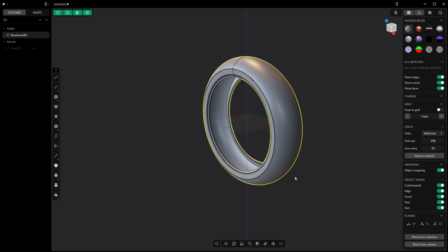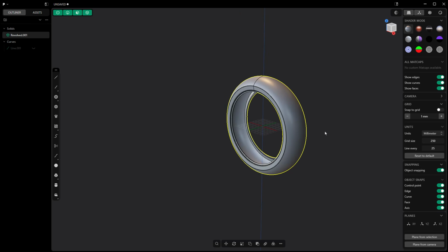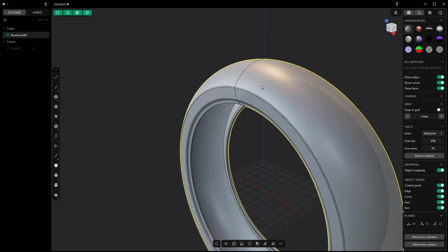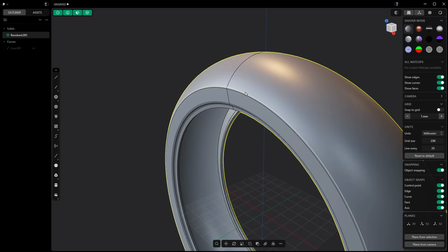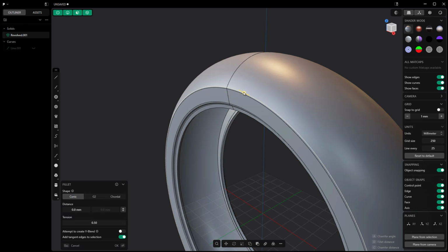The next step of this process is to identify and understand that most of the time when we have treads cut away, or these grooves that allow the rubber to deform, sometimes they're for water or dirt extraction, whenever we have these, they typically will exit the tire basically exactly where the outside surface is, and they'll be deeper in the center. And so generally, they're exiting before this edge right here where it rolls down to the sidewall.